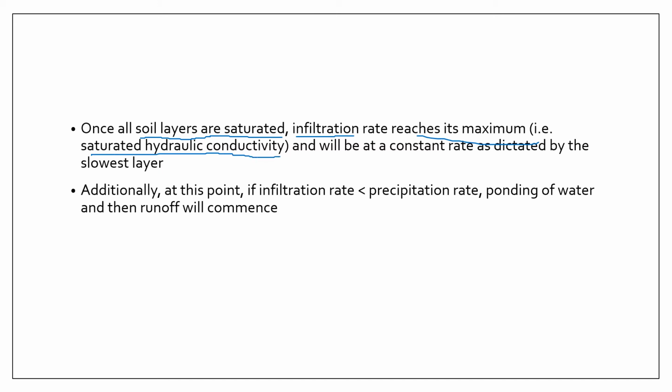So now don't confuse this with the earlier chart I showed you. I think I showed you a chart showing the curve of the infiltration rate, as modeled in the SCS-CN method. So in the SCS-CN method, what makes your initial infiltration fast is the storage and the spreading out of your precipitation. Okay?